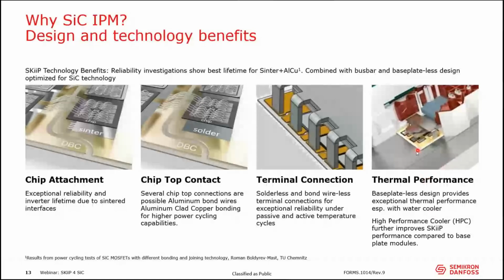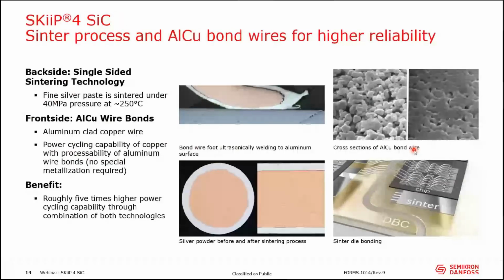We also have no base plate, as can be seen in the picture. So with a high performance heatsink and high performance thermal grease, we have good thermal performance so that small silicon carbide chips can be cooled properly. We will discuss all these topics in detail now.